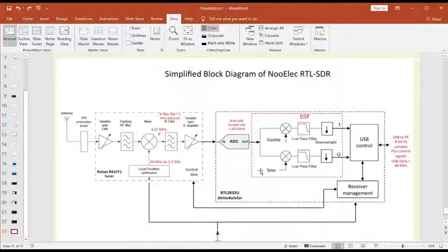And why is that a problem? Well, it's because in reality these sine and cosines are never going to be 90 degrees exactly. The power levels between this chain and this chain are never going to be equal in analog hardware. But when you do that all in digital, there is effectively no hardware because all this functionality is being done by basically number manipulation, okay?